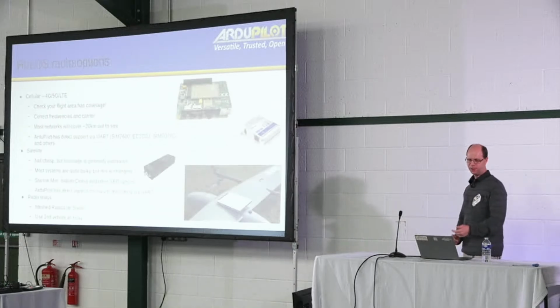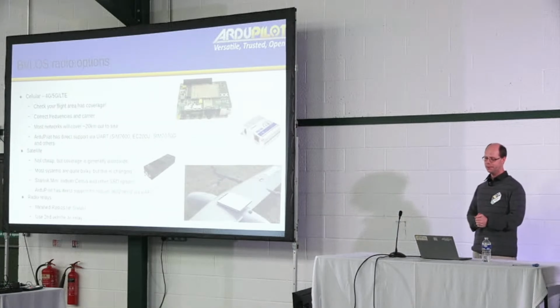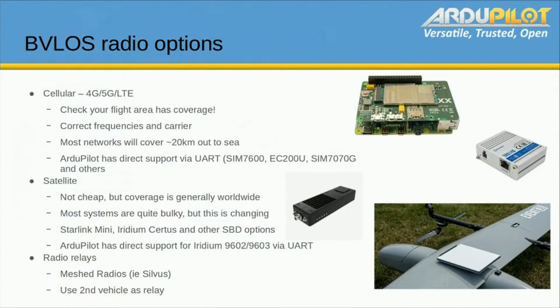All right, my favorite bit, radio options. These are the sorts of options that, if you are doing BVLOS flights, practically, what options can I use as of the time of writing, so mid-2025. There are your obvious cellular options: 4G, 5G, LTE, pick your flavor.